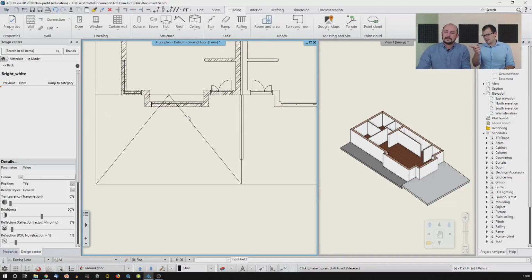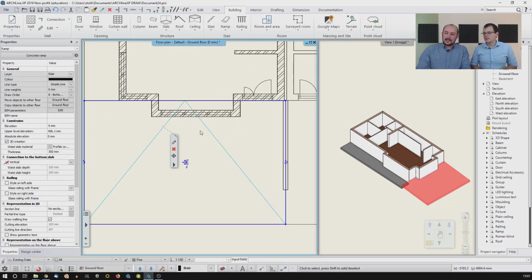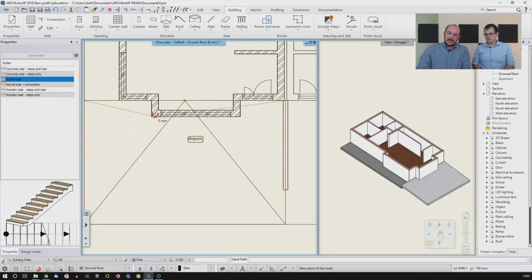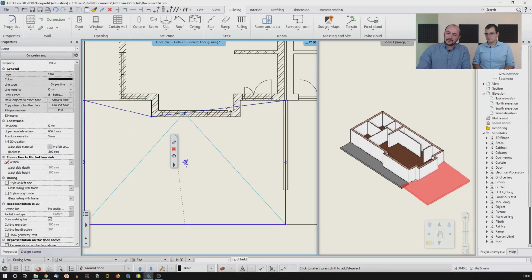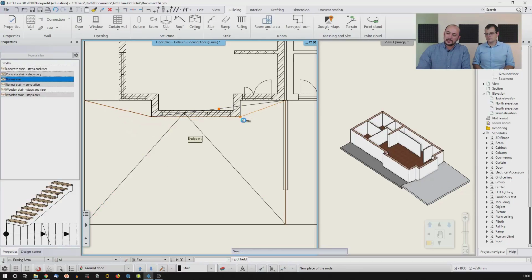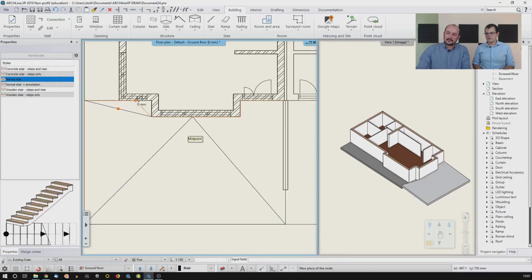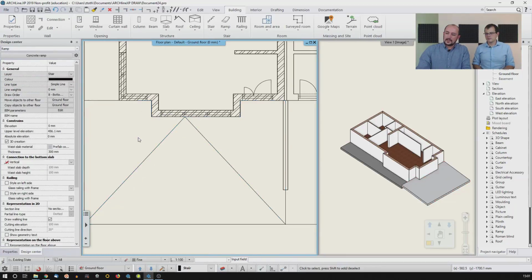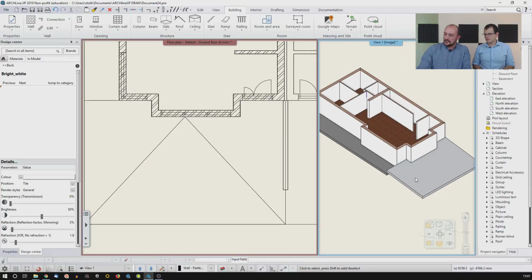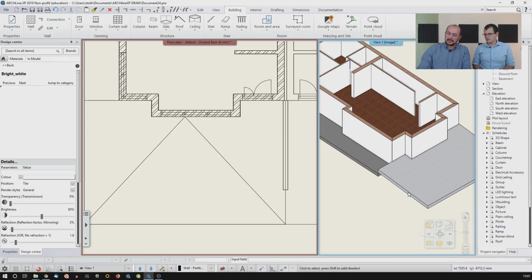How do we modify the contour? Because we can see up north that it's not good. In that case, again, I click on the edge. I use the insert node point, and like these are tiny pins, I just pin them to the proper point of the drawing, reshaping this whole design. And then I see another issue with this. It's actually not perfectly matching the original design, so I need to change the inclination and the height.